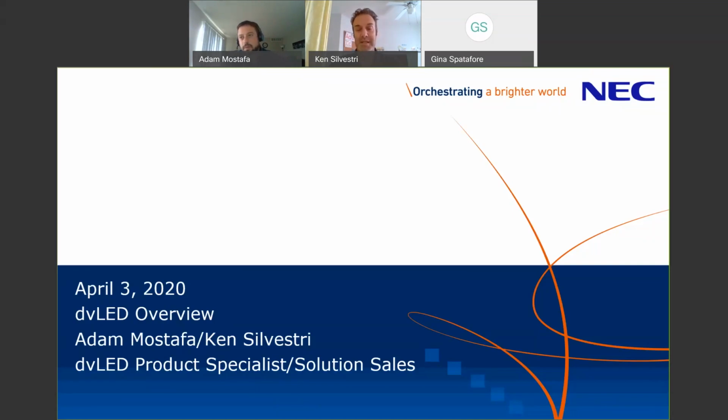If it is in a space that is relatively open to the public, we also ask for a PTZ, pan, tilt, and zoom camera, to be installed someplace close by so that we can also have access to it. So when someone calls us, hey, I have a problem with my wall in this location, not only can we get into the controller, we can also see what the wall looks like and try to resolve that remotely. That should be a frontline option for service whenever possible.